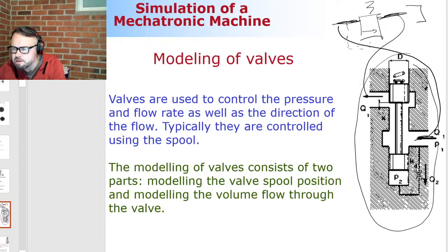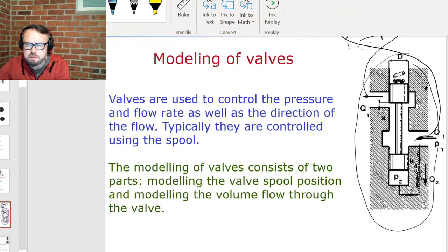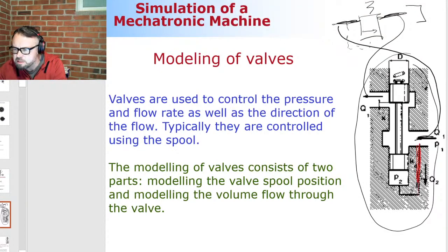And then I have here small drilling, which it's maybe a little hard to see because I'm using the black color, but let me change the color to be red here. So this is this pilot drive. The pilot drive is here, this dashed line. The pilot drive comes here and is introducing the pressure P2. And the pressure P2 is actually a little less than the P1 here because throttle that is here. Not clearly visible, but there is a throttle here that is introducing pressure loss.